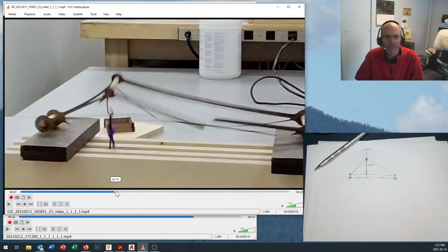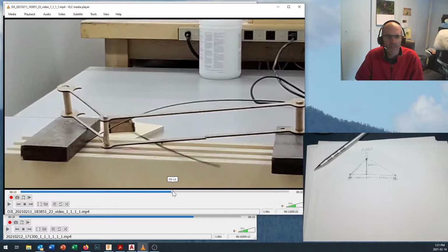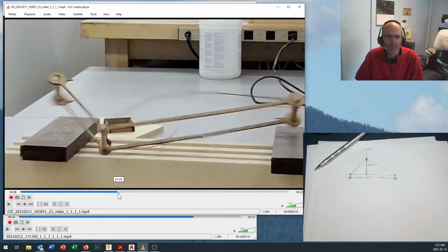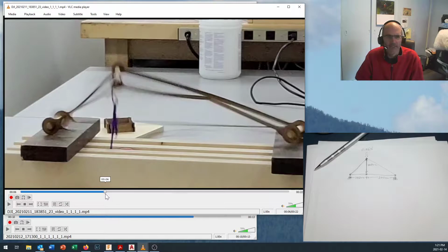first? You can see that by the time this structure is lying on its side, the tensile members have snapped. We've got a snap right here in this compressive member, but did it fail in tension or did it fail in compression? That makes a big difference to where we're going to go to strengthen our structure. And when we play it back in slow-mo, you can see right there that that was very clearly a buckling